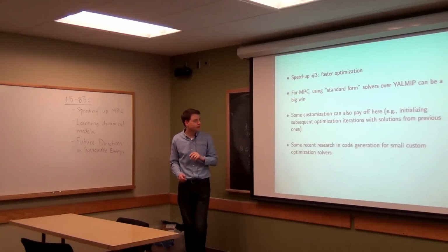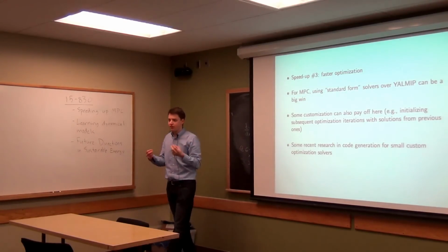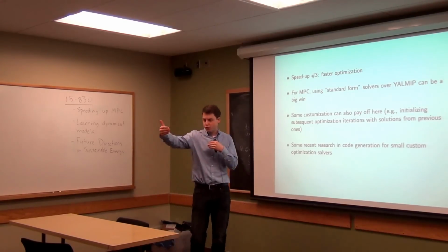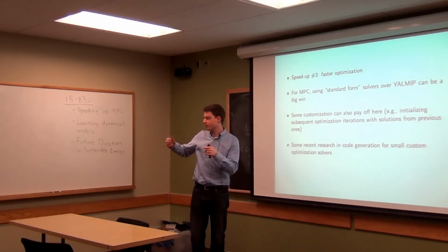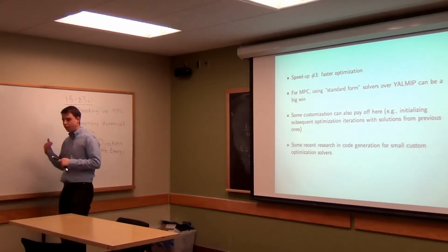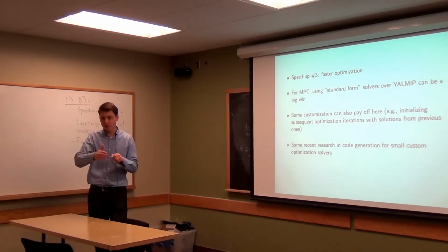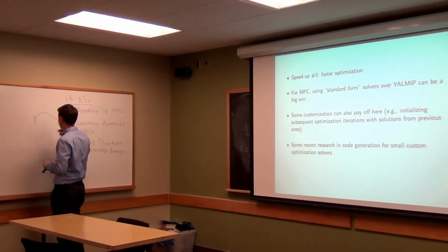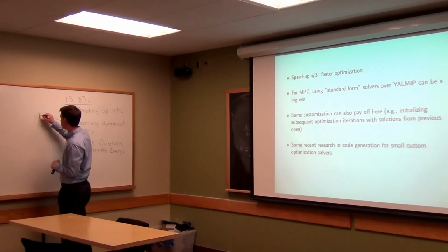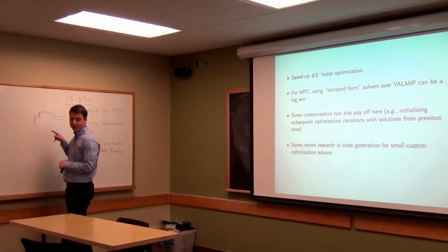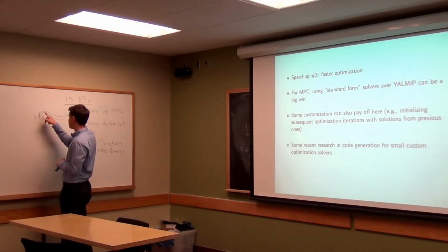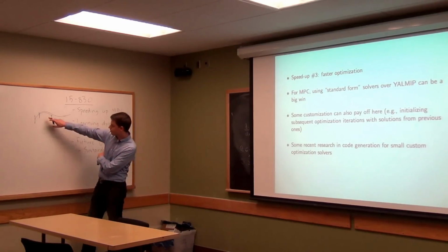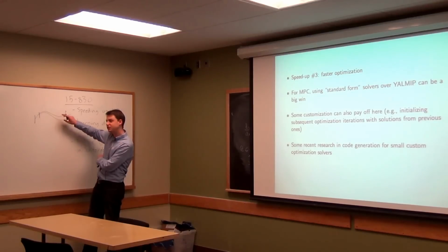There's also been a lot of work on speeding up optimization in clever internal ways. So remember, the idea of MPC is that we're solving these long tasks one after the other. We still typically have a time horizon that we optimize over that's much longer than the time between updates. So at time t, we solve some set of control inputs. Then we move forward a little bit, and we solve some new set of control inputs that might have changed, since we are not quite in the state that we thought we were in.